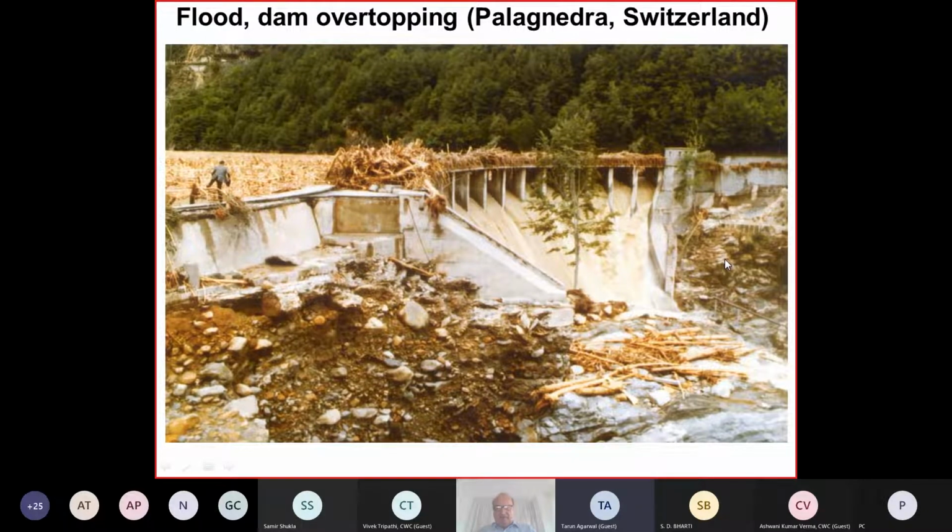But the characteristic of our floods is that the catchment areas are relatively small, so the floods are of short duration. They have a high intensity peak, but they don't last for hours, they last for a relatively short period of time. So based on this incident, until that time, for the spillway design, it was assumed that the water is clean, no floating debris.